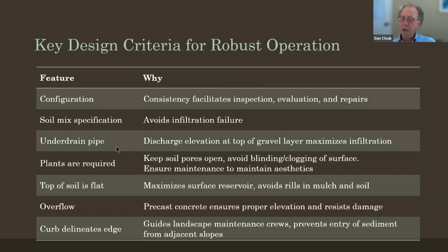But at each of these, the location of the underdrain pipe, the soil mix specification, the consistency and the configuration, having the top of soil be flat, requiring plants, having a precast concrete overflow, having a delineation of a curb around the edge that shows where the facility is.